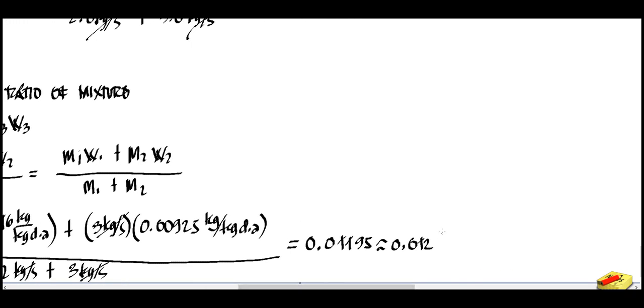So that will be the humidity per kilogram of dry air. So it will be the humidity ratio. Since it is grams, let's multiply it by 1000. So we have the value of 11.95, which will be grams per kilogram dry air. Okay. Sorry, this is already 12 pala, so we'll change it to 12 since we rounded off. Sorry for that one. This will be 12 grams.